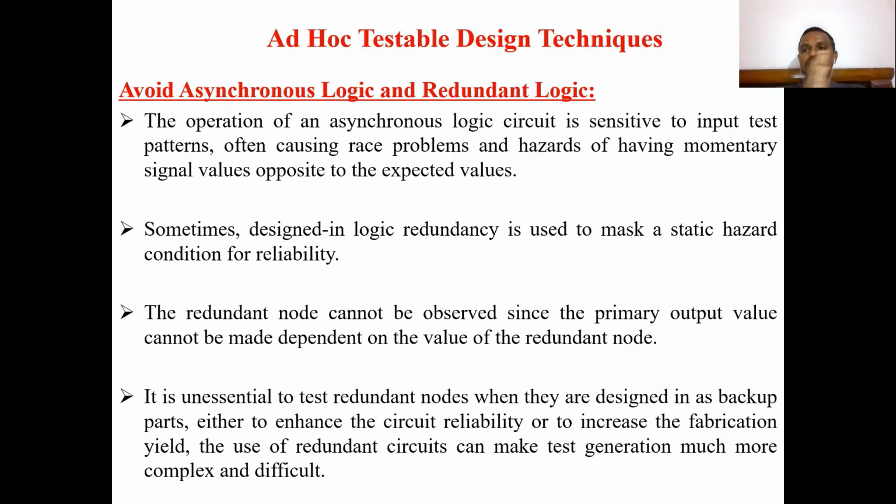If there is a signal delay, that is, if the input cannot reach the input terminal in time, then the previous input value will be applied, so the output we are getting is for the previous input value, not for the present value. That is a problem for us. That problem is called hazards. So this is about hazards. Hazards are nothing but problems due to the delay in the input values reaching the input terminal.